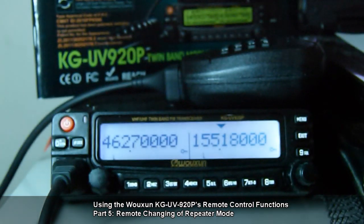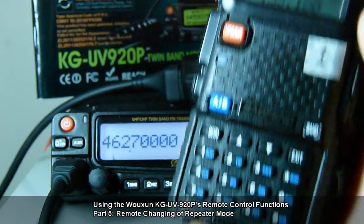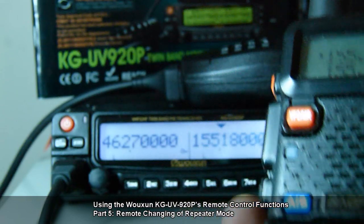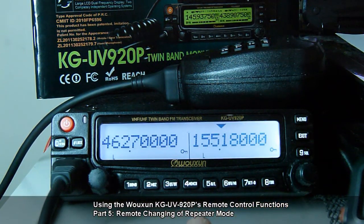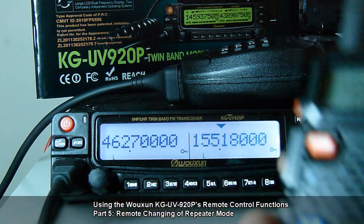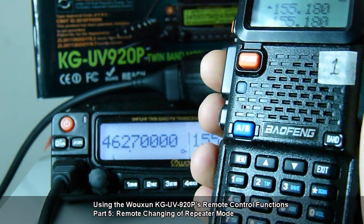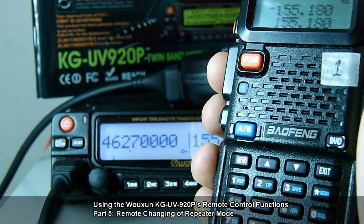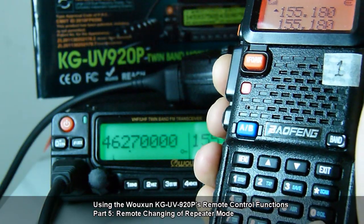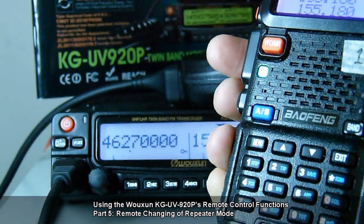So let's try it right now. I will be using a Baofeng UV-5R as an HD controller. So to change from normal communication mode to directional crossband repeater mode, we will do this. So that's press the PTT, and then 1, 2, 3, pound menu down, release the PTT.